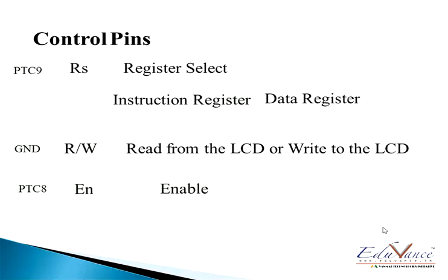The reason for that will be we are going to write to the LCD and not read from the LCD. And enable will also be connected to a pin number PTC8, which I'll tell you in the code itself, because these are going to be the programmable pins and we are going to give a high-low, alternate high-low depending on what we want to do.